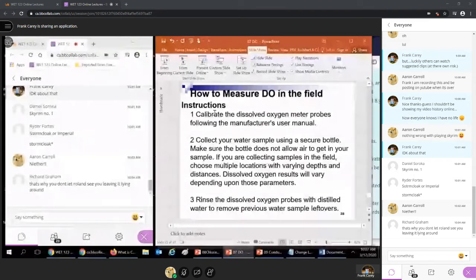Then get proper sample bottles. If it's a laboratory that you're bringing it into, get the sample bottles that they supply. That is of utmost importance. Of course, once you're out in the field, people kind of forget the proper way to do things. They'll use their shirt to clean vials instead of the proper velvet cloth, or just grab any sample bottle.